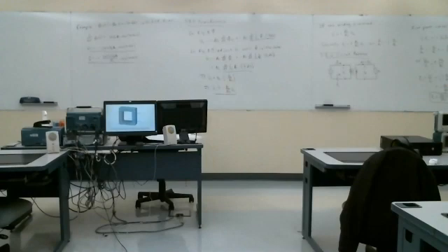It's not convenient from a schematic standpoint to be that detailed and give some sort of 3D representation of the actual transformer windings. So the convention is to actually put a dot at the terminals representing the assumed polarities.